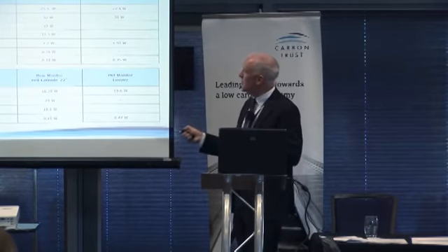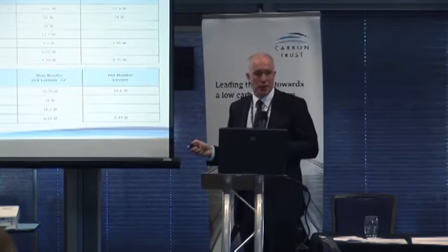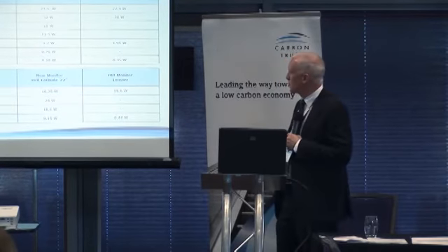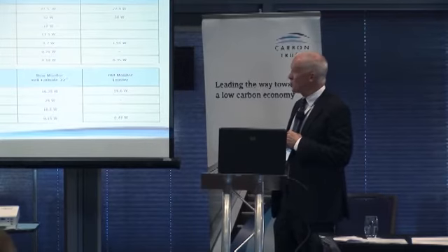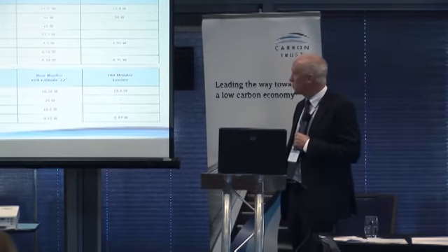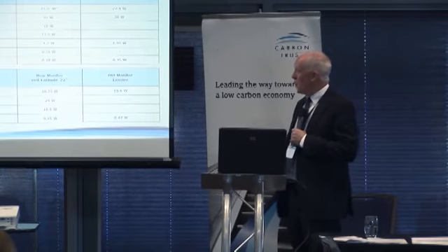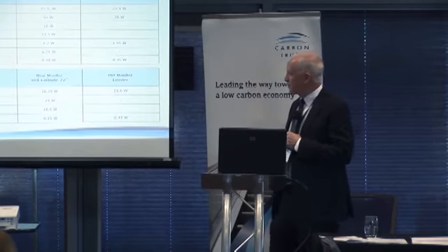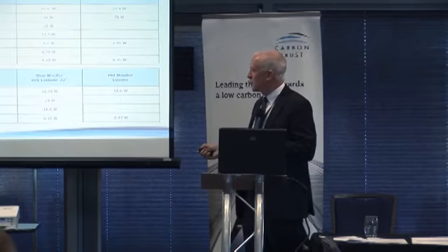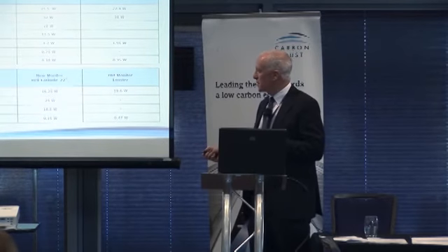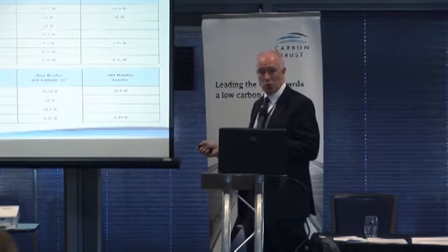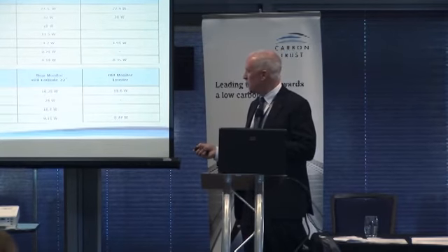So I think you're getting an idea that things are generally improving within a selection of laptops. The old monitor used about 20 watts, this is the large external monitor. The new monitor, 16.25 watts, it's a large 22-inch screen. On 100% brightness, that went up to 24 watts. On 50% brightness, it was 18.5 watts. So the smart mode that looked after the brightness of the monitor was actually more efficient.